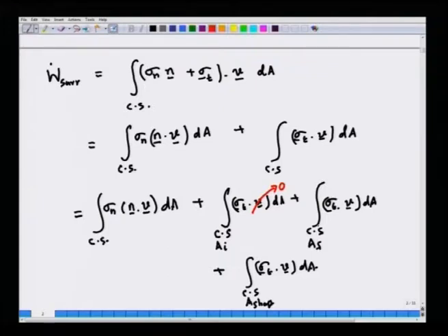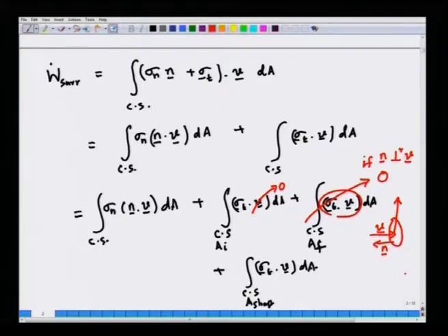If you look at the control surfaces over the flow areas, let us say this is the flow, this is the direction of velocity. If you choose the control surface perpendicular to the flow direction, then the tangential stresses will act in the direction perpendicular to the velocity. So, these 2 vectors are orthogonal, and this can be set to 0 if n is parallel to V. That means that the velocity vector and the shear stress vector are orthogonal to each other.